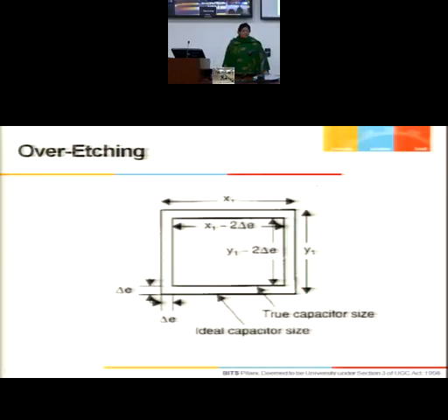Is this clear to all of you how to retain a control on W by L? Sorry, this unit component, use of multiple unit components helps us in having a control on the ratio. Same thing we do for matching transistors also. Each transistor is made up of numerous multiple components, so that W by L of 1 is same as W by L of the other.